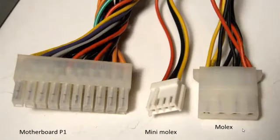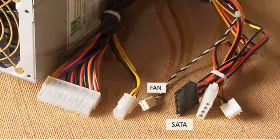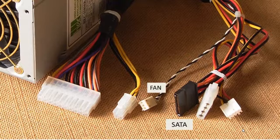Now, there are many cables that come off a standard power supply, and there are many connectors at the ends of those cables. Some of the common ones you can see on this screen: the motherboard P1 20-pin connector, the mini Molex that was once used on the floppy drive, and the Molex that was sometimes used on optical storage as well as mass storage devices. On a modern PC, you can expect to see SATA connectors, a small power connector for a fan, and an optional 4-pin connector power supply that's sometimes used on things like graphics cards.